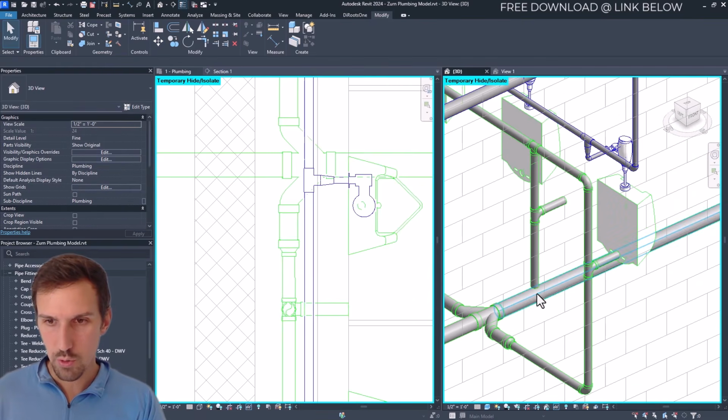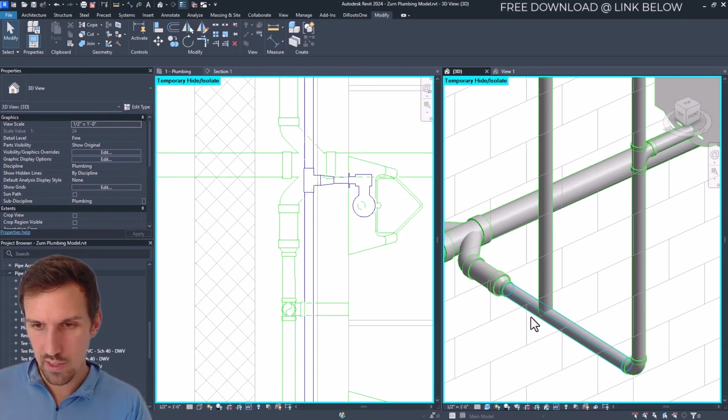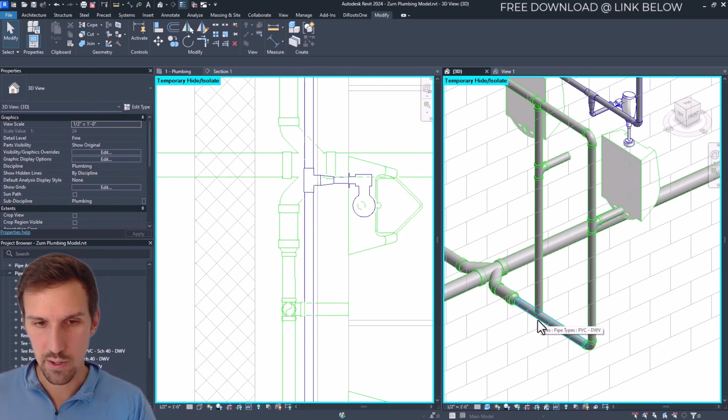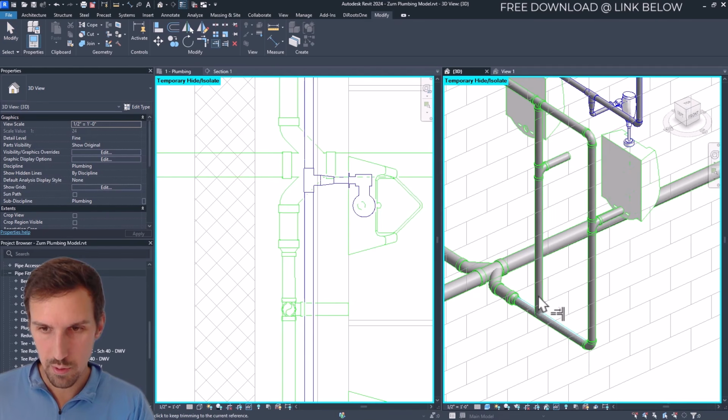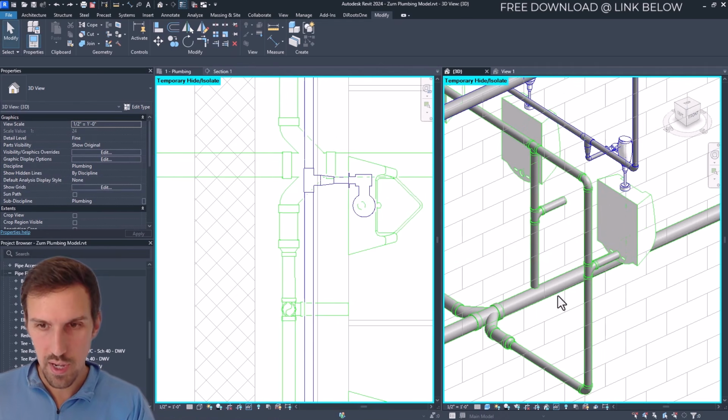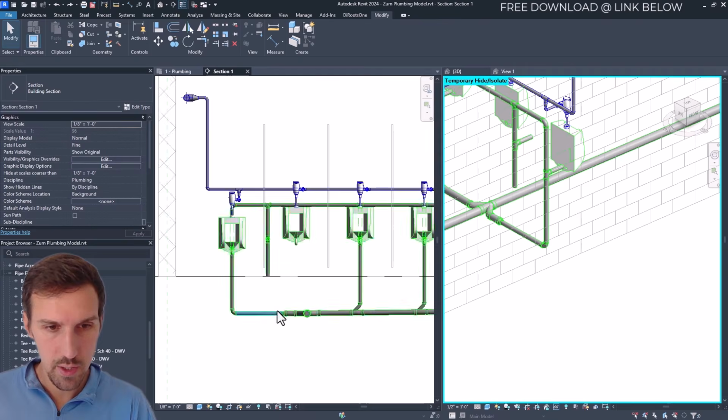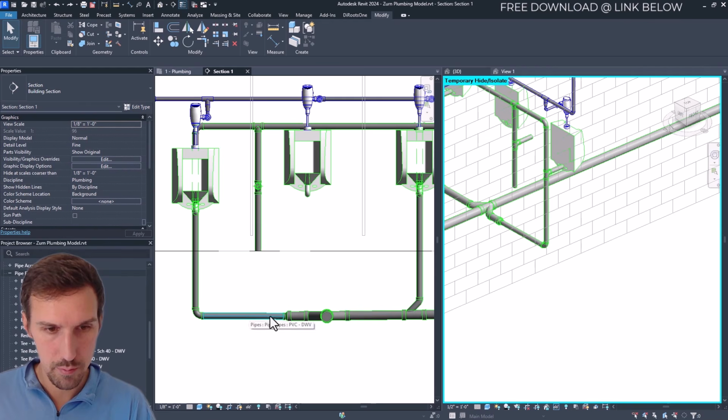Let's go ahead and trim into this piece right here. So we're going to go to our trim extend single, click, click. Unfortunately, it didn't look like it made the connection, so that's not great. It's probably because it's not completely lined up correctly. And so sometimes when that happens, you might have to go back to your select. So let's connect from this main right here up to this one.